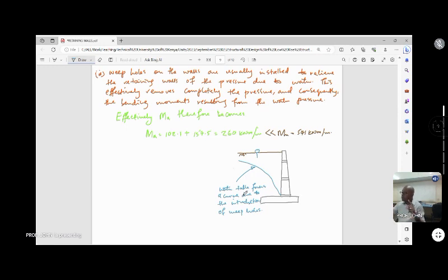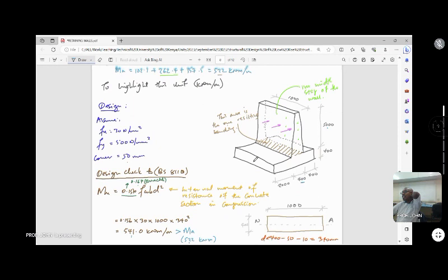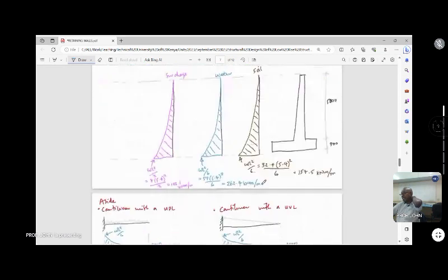Now, effectively also, that means that we cannot take advantage of the effective density of the soil. Once we ensure that the water table does not touch the wall, then we have to work with the true density of the soil. And that's why I did not change this density to effective density.